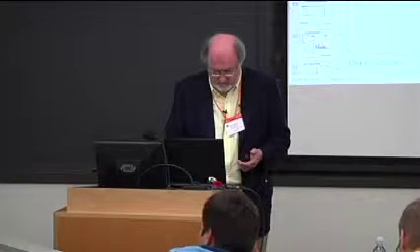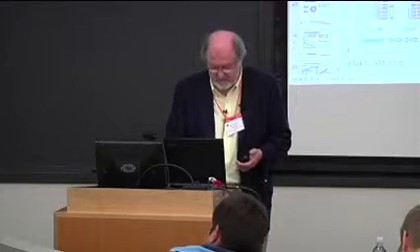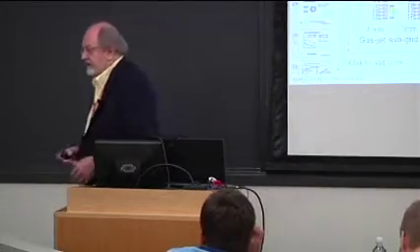Regarding the issue from a couple of slides ago, we had the spray model that needed to be grid independent. I was just wondering if you changed the number of parcels or the number of droplets per parcel as you change the size of the grid, if that would also have that effect?